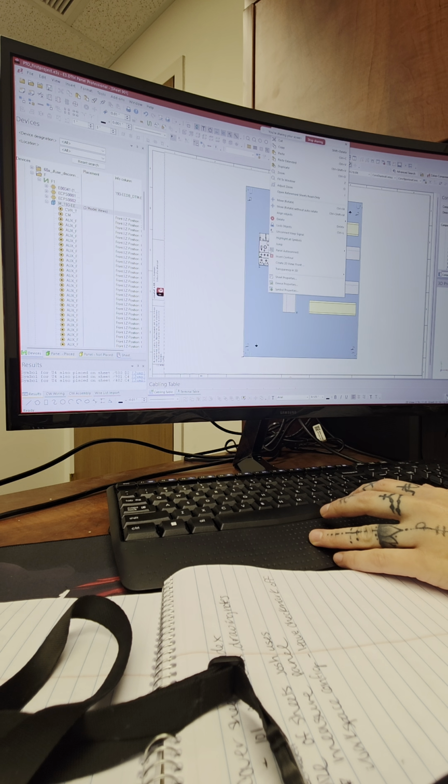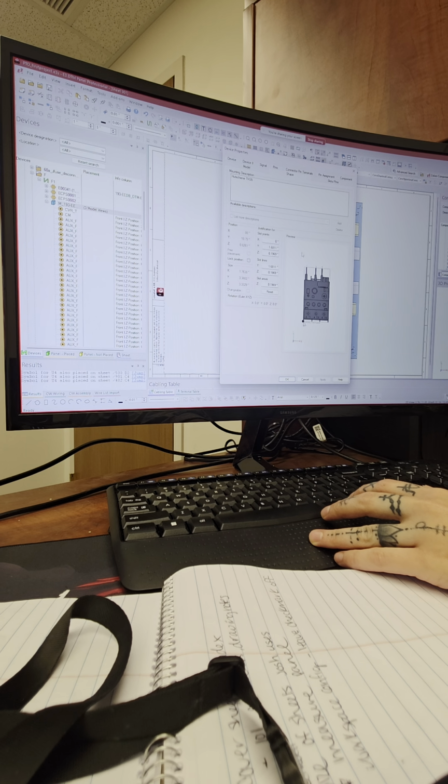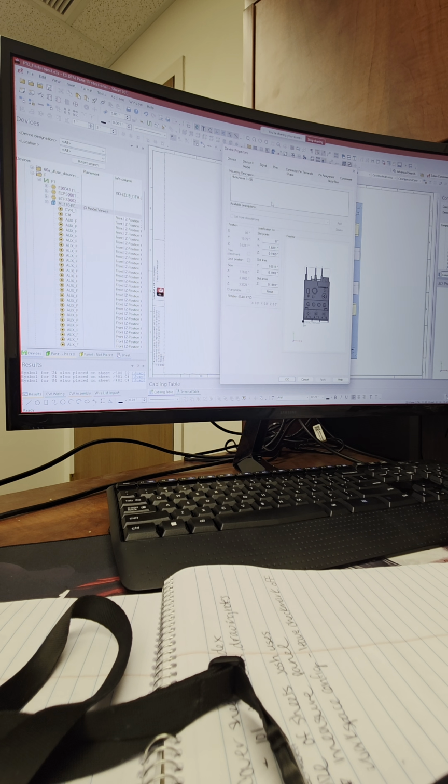Right click on this component. Let's click on device properties, and let's click on shape. That's usually where all these mounting descriptions are stored. So in this case, and again, this is a longer story, as you go to the component cloud, it's using a feature called CLX. It's an application that allows you to go to component cloud, find your part, and as you're downloading the part, that CLX plugin goes directly into your library itself.